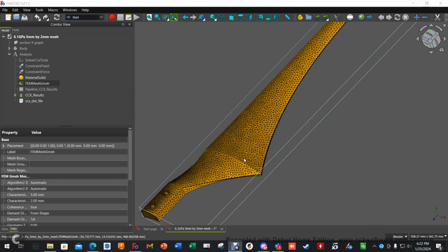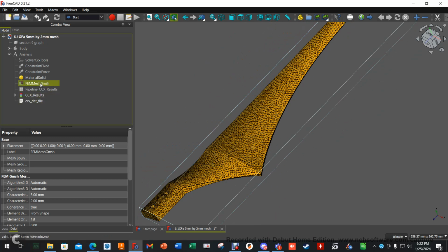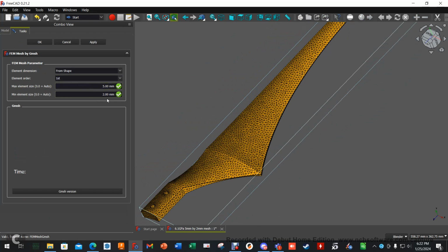Anyway, last time we went over the mesh and how to generate it using Gmsh and how to fine tune it until you get at least no errors in the mesh and something that works pretty well. You'll notice last time I had a first order and also a second order, and I said second order is more accurate. That is true. However, today we're going to learn that even with a first and a second order, you can get instability with your meshes, and that's what I want to go over.